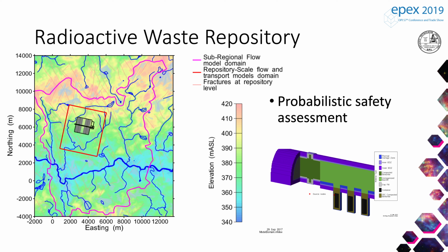So hydraulic conductivity, or permeability, unfortunately, this is all in funny units of meters per second, but controls contaminant transport. But below a certain threshold, it is no longer important, because diffusion, which is just transport along chemical gradients, becomes the dominant process. And that's where you want to be in a rad waste repository. You want to be in that diffusion-dominated regime, because it's much, much slower transport.